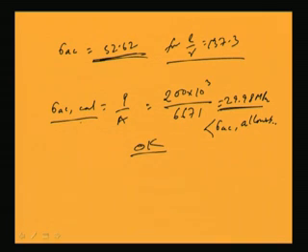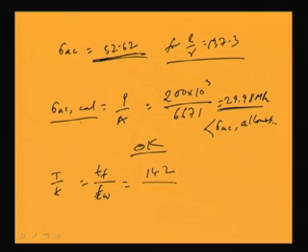So here we have to find out first T by t, which is basically thickness of compression flange, TF, and then thickness of web, TW, right. So thickness of compression flange is given 14.2 and thickness of web is given 8.1. So this is coming 1.75.